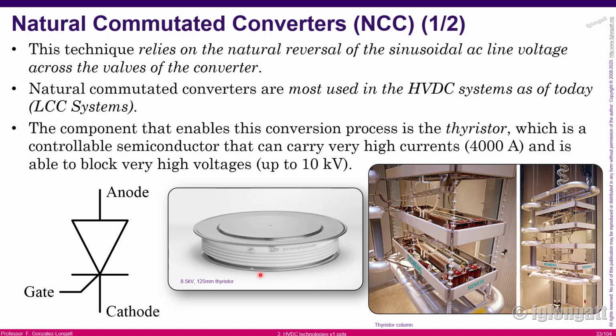Thyristors have the property that we can close them using the gate, but we need to wait until the sinusoidal AC voltage across the converters opens again or resets the thyristor, okay? What is the good news? Those devices have been many years in the market. They grew in size, they grew in power, and as a consequence today they are quite dominant in high power, high voltage applications, okay?